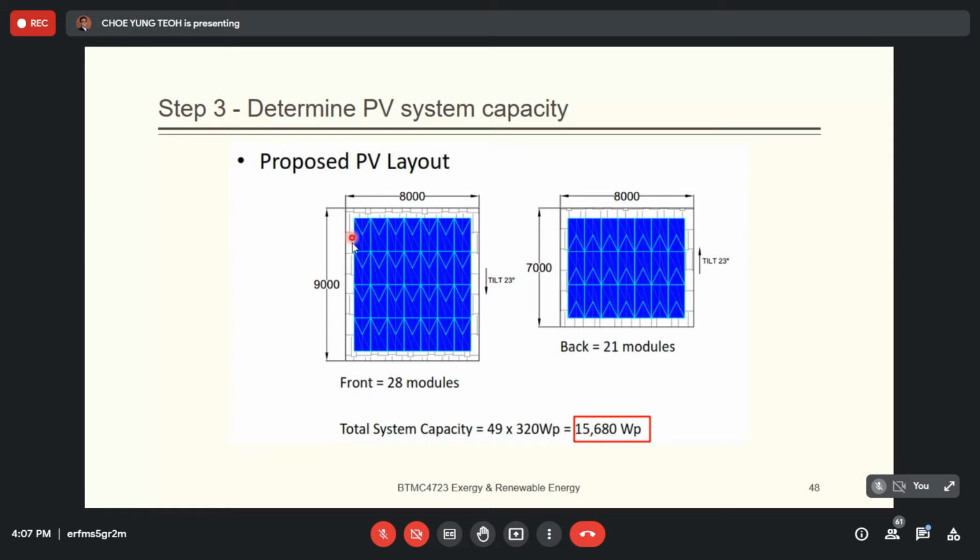When a shadow falls on this panel, you should have a bypass system to bypass this panel, or else it will become a resistance to the system, something like an accident happening on the highway. So remember, shadow is very important. Try to avoid it. If you know that you cannot avoid it, the shadow must be there, and you need more power so you want to fully utilize the space, then you can consider using the bypass system.